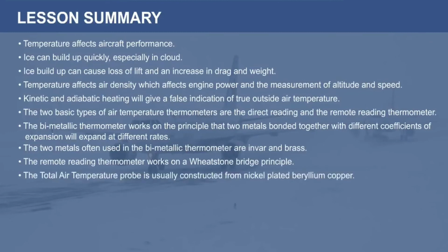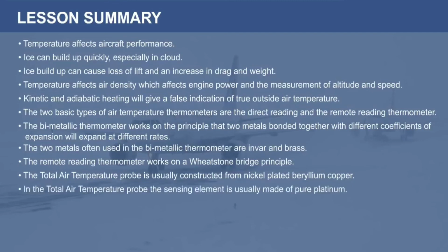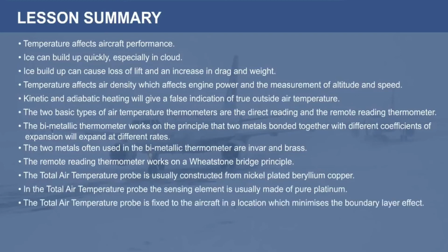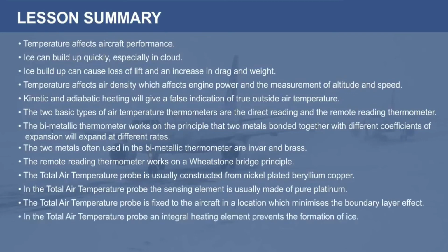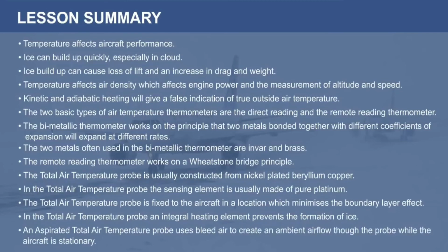The total air temperature probe is usually constructed from nickel-plated beryllium copper. In the total air temperature probe, the sensing element is usually made of pure platinum. The total air temperature probe is fixed to the aircraft in a location which minimizes the boundary layer effect. In the total air temperature probe, an integral heating element prevents the formation of ice. An aspirated total air temperature probe uses